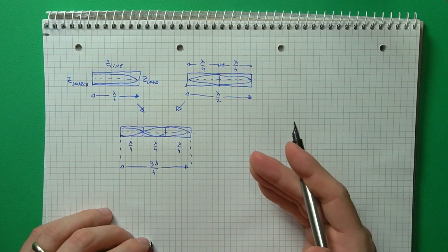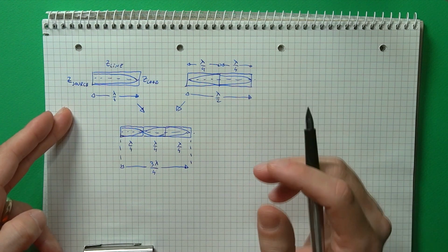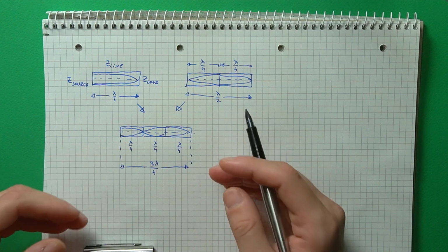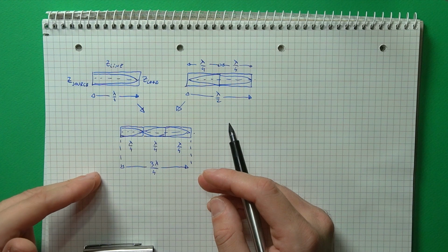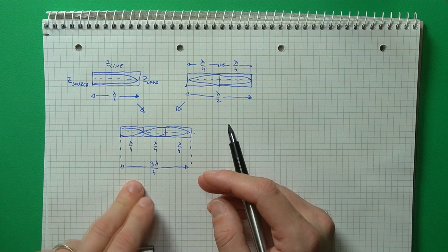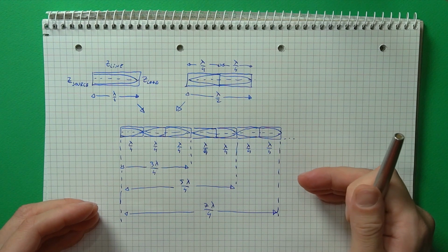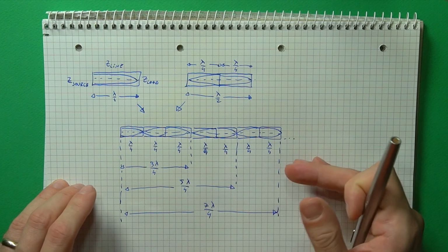But if we put together a line that is inverting and a piece of line that is not inverting, together they form a line that again generates a phase inversion. So this occurs again for a line that is 3/4 of a wavelength long. And then for other higher multiples, where we have an extra half wavelength segment added on.